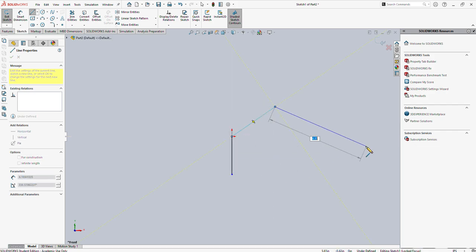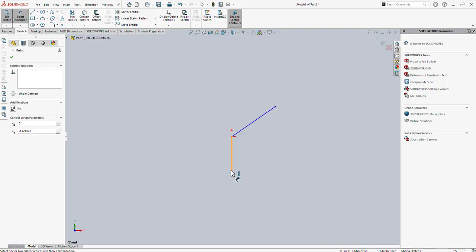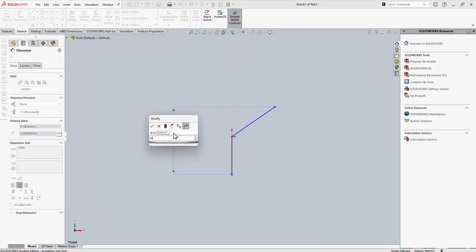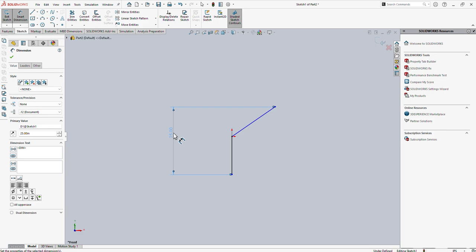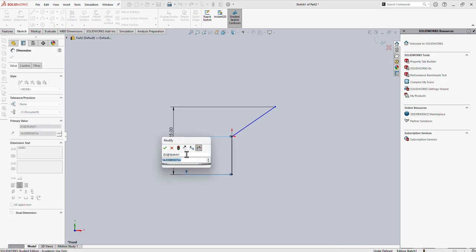As I showed you earlier how to define your angle, we can draw a construction line straight and define our angle in between, or if you just want to play with your numbers, you can also do it. So for our exhaust system, this down tube, the total height will be, let's say, 25 inches, and this vertical one will be, let's say, 15.